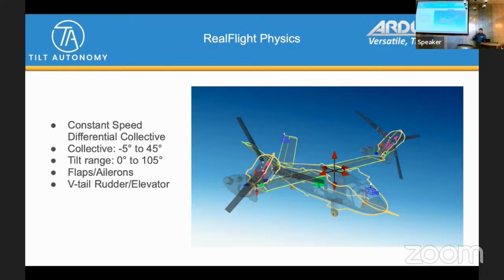The interesting thing that I found with respect to tilt rotor in RealFlight is because it is so symmetric, the hierarchy that you end up building is very, very simple. There's very few things that you have to put in. So a symmetric wing, in this case a V-tail, so a symmetric tail, and then the tilt mechanism on the end, and then attaching the motor. And it's literally one element that's just duplicated to the other side.